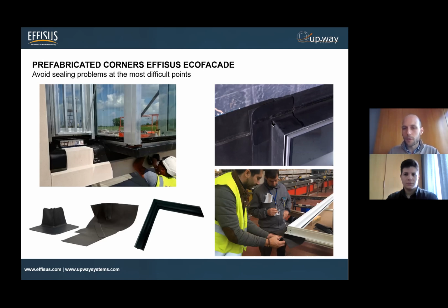for instance. Then you need always to cut the membrane, the edge of the membrane here when it's reaching, for instance, this side membrane, when it's reaching the top, you need to cut in here. So you'll have here a direct hole to the inside. And then the same occurs with the membrane that comes from the top of the window, and that has to be cut just right here, and the same specific hole will be created in the same specific point. So there's no chance of doing this in a different way, or at least this is the most common way of doing this kind of details.